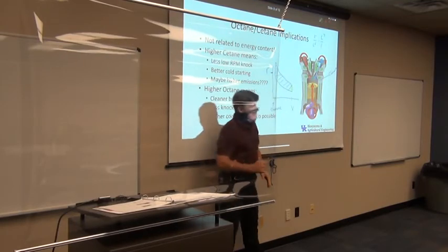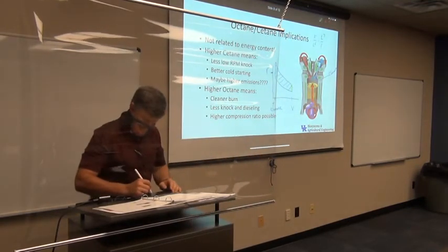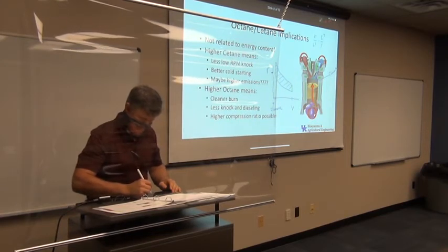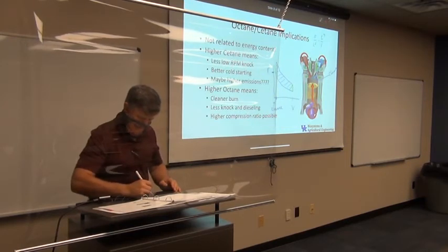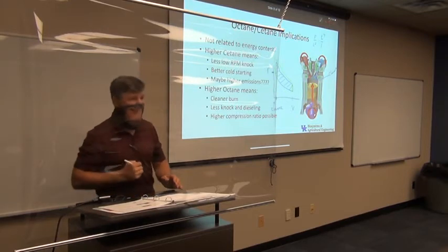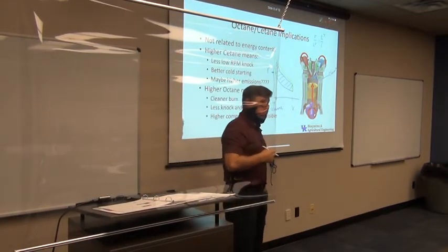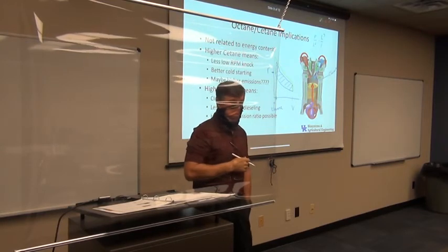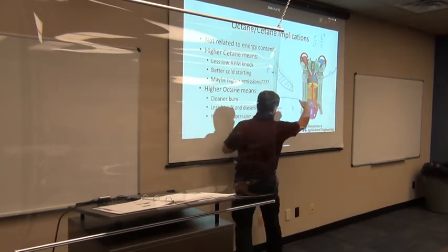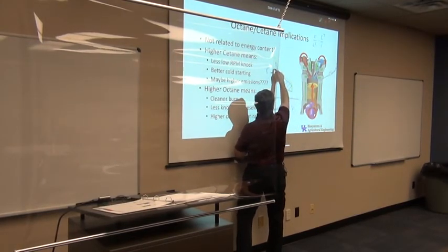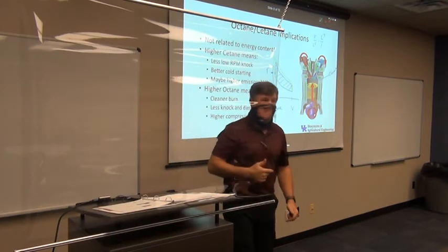If I move that over by the same amount, what does that do? So here's my clearance volume. I cut that clearance volume in half, or make it smaller. This curve comes way up because it's an exponential curve. It comes way up before it hits that, and I get a real big spike in pressure. I open that curve up like crazy by reducing that clearance volume. Okay? You see what I did? Can you follow that logic? Reduce that clearance volume, and because of the shape of this curve coming up, it's going to make that pressure jump up pretty significantly.